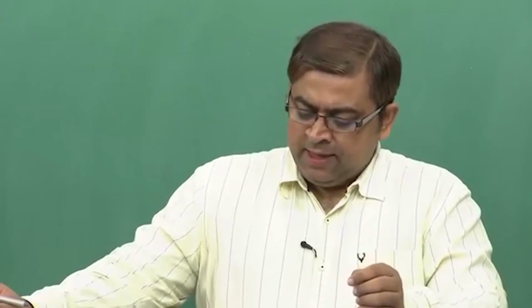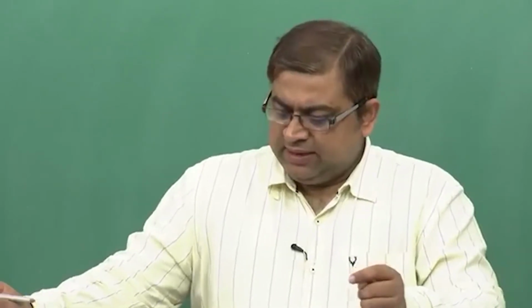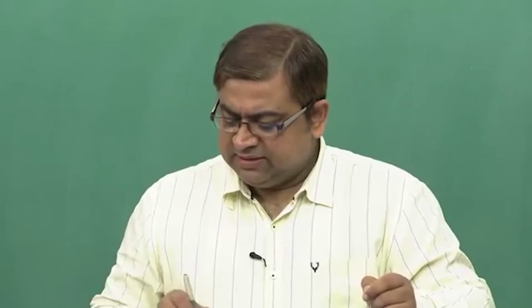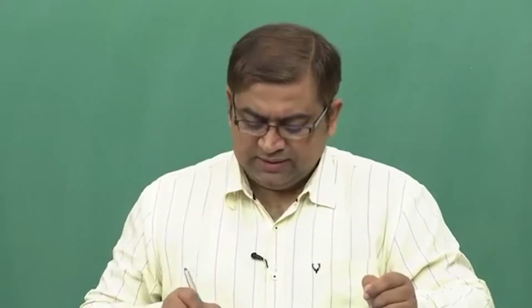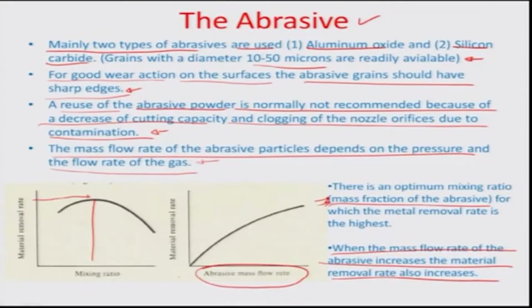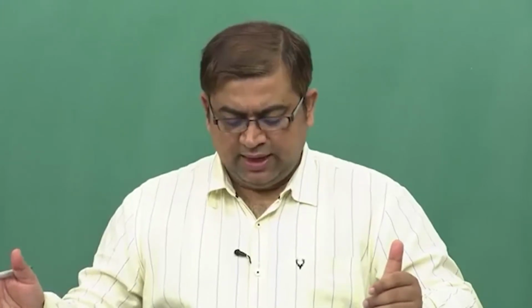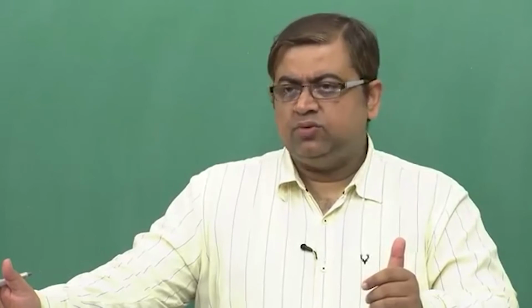And the other issue is that when the mass flow rate of the abrasive increases, the material removal also increases, but this is again subject to an optimum. If the mixing ratio is the same, and you keep on flowing the air abrasive mixture and hitting on the surface, then the higher the abrasive mass flow rate at a certain mixing ratio, the higher would be the material removal.